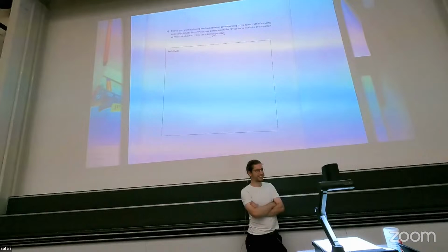Now, I also have Mealy type operations, where the present input can directly change the output. If I sample the output here, I also want to give enough time so that the output can be calculated properly in the same cycle. This is the reason we are doing this.